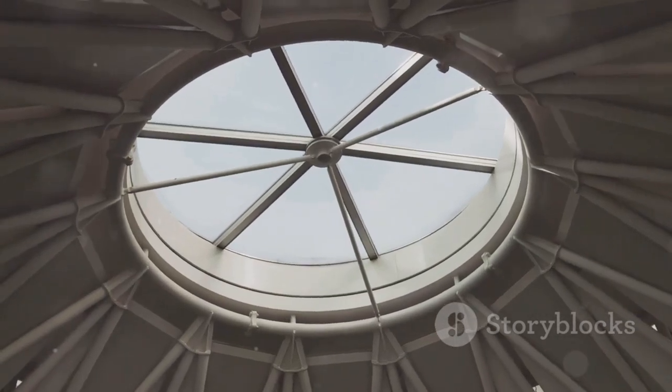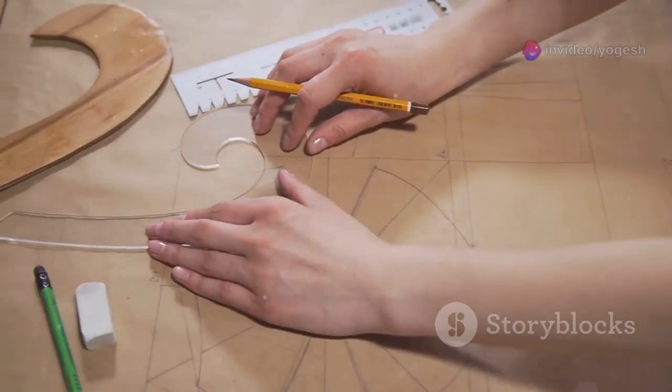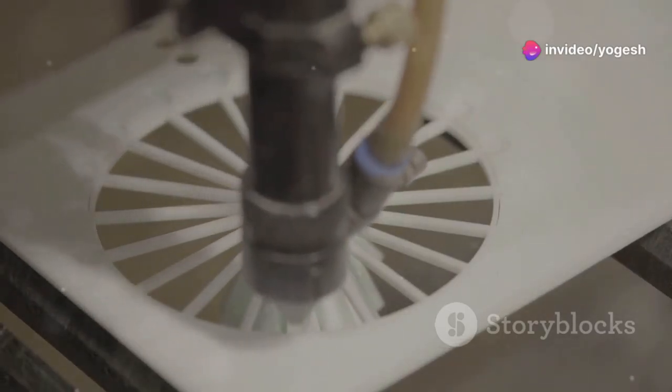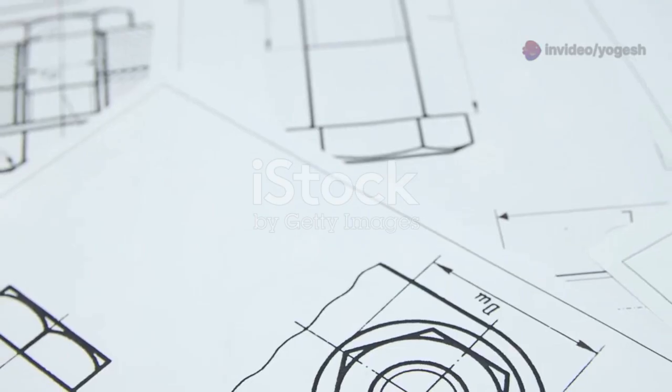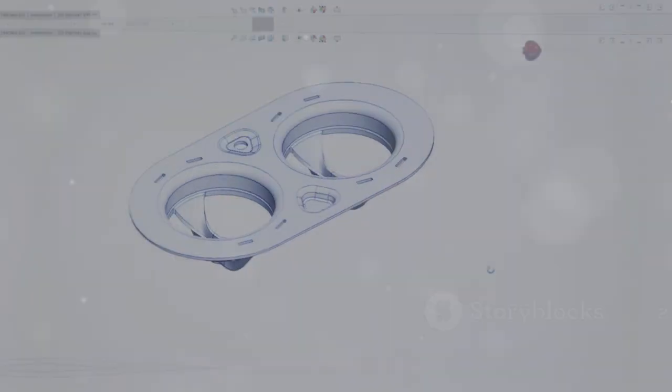Project features to create Section AA. Hatch lines show solid material. Voids remain empty. Ignore the jogs in the cutting plane for a continuous view. This reveals the bore, keyway, and bolt holes clearly. Sectional views simplify complex parts.